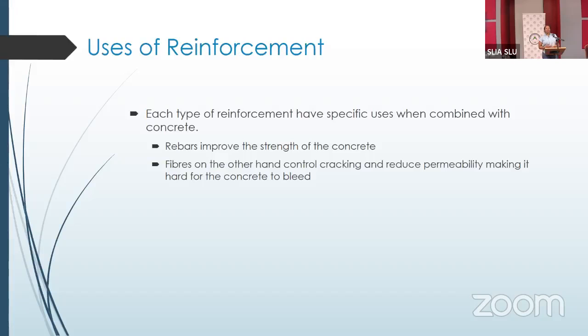We do not want our slab cracking, even if it is directly on the ground. We don't want moisture getting into that concrete because, especially if we were in a temperate country, unfortunately for us, we aren't, that water can get into your concrete. At colder temperatures, that water is going to expand and cause the concrete to crack, which means that your concrete is going to fail.